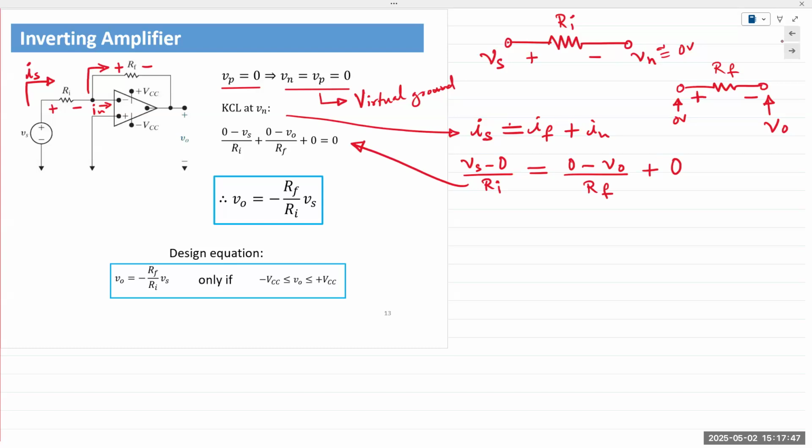In chapter 1, when we did the fundamentals, current always goes from high to low, from plus to minus. Conversely, if you have plus to minus, then current is flowing from plus to minus. The point of entry is always plus, the point of exit is minus. So if we assume a current direction, we can assign a polarity. If we assume a polarity, we can assign a current direction. In this case, we have power supply Vs.